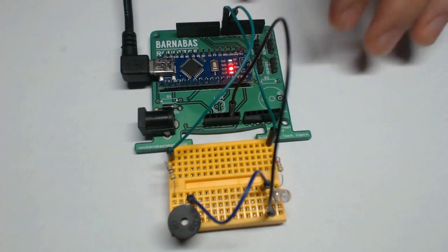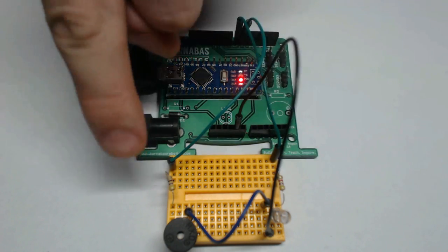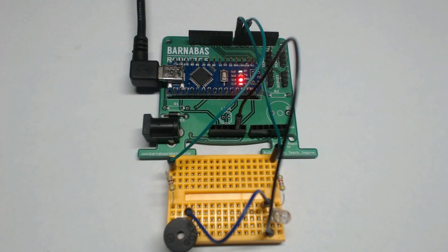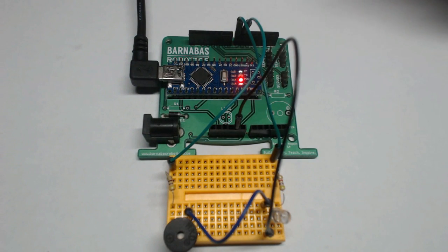So it's not an obnoxious volume, but you can imagine maybe 20 kids having this going at once. It might get a little overwhelming. So something you can do is just swap those two resistors, have the 470 ohm over here and the 4.7K over there, and that will bring the volume down of that. Of course, that creates the problem with the LED being a little bit brighter as well. So keep that in mind.